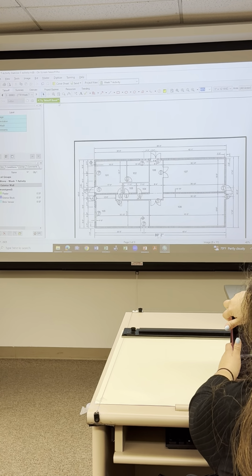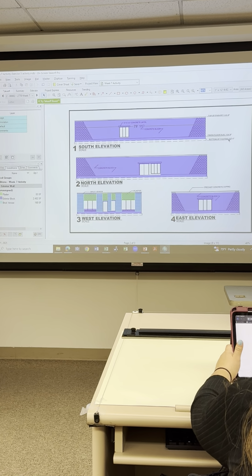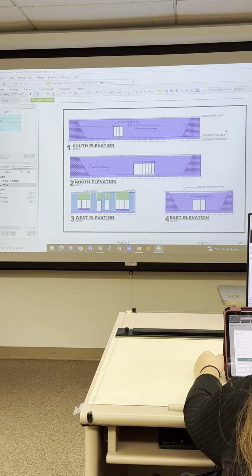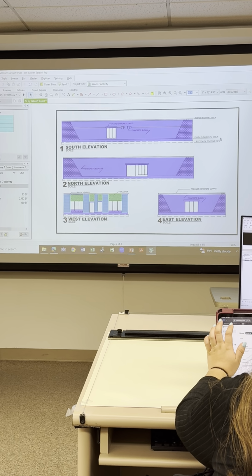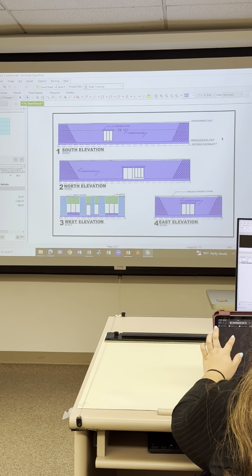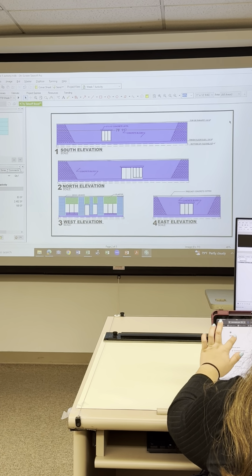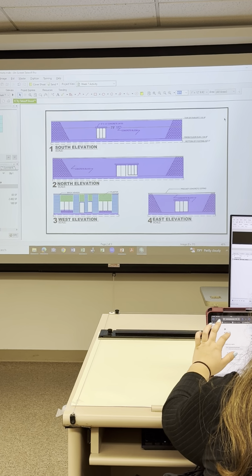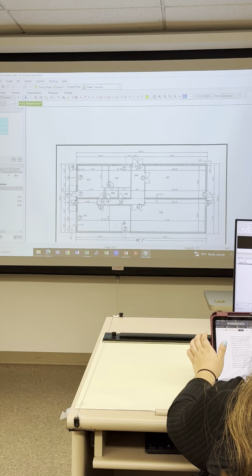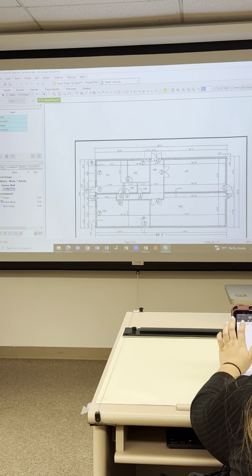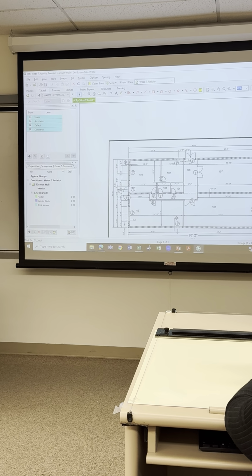I also know from the elevations that the bottom, the finished floor to the top of the parapet, it looks like, here I'm generalizing, is going to be 11 feet. Yep, I have that right. From 104.8 to 115.8, top of the parapet is 11 feet. We're going to assume that interior wall is a full 11-foot height. So I can create a condition. I'm going to first do a new folder. I'm going to call the folder interior walls.